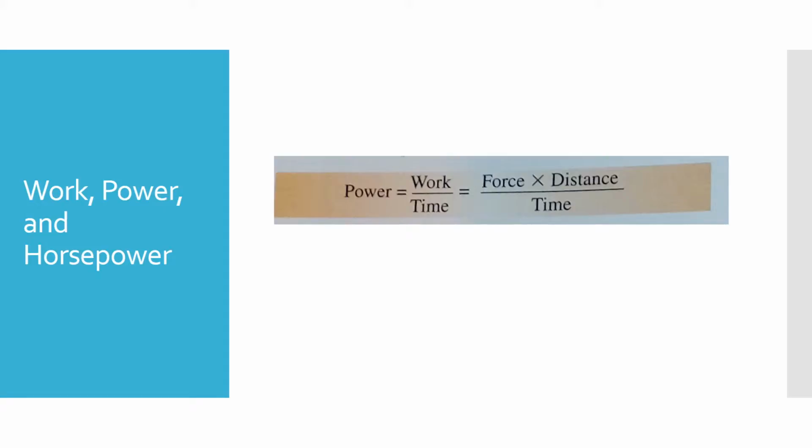In electricity, the unit of power is the watt, capital W. It was named in honor of James Watt, who is credited with the invention of the steam engine. When 1 volt of electrical pressure moves 1 coulomb of electricity in 1 second, the work accomplished is equal to 1 watt of power. Recall the definition of the ampere, the movement of 1 coulomb of electrons past a given point in a circuit in 1 second. Thus, power is in an electrical circuit.